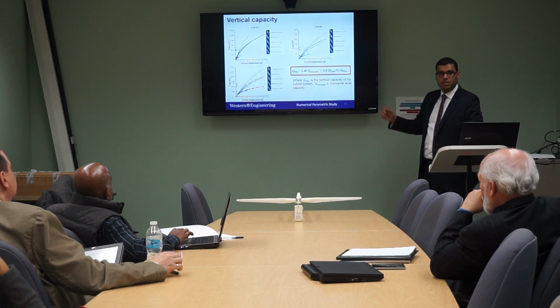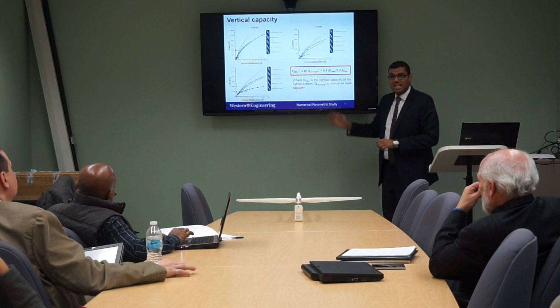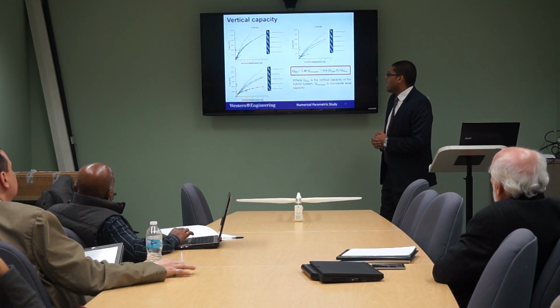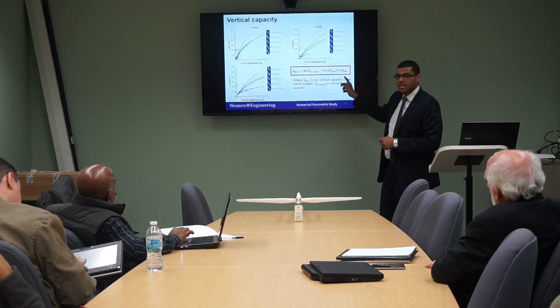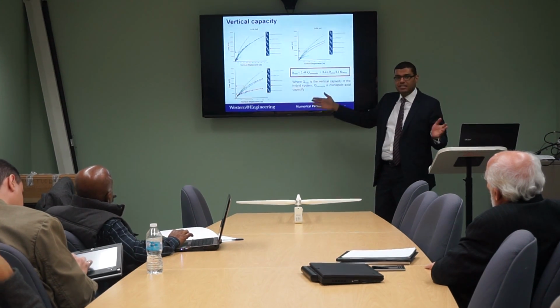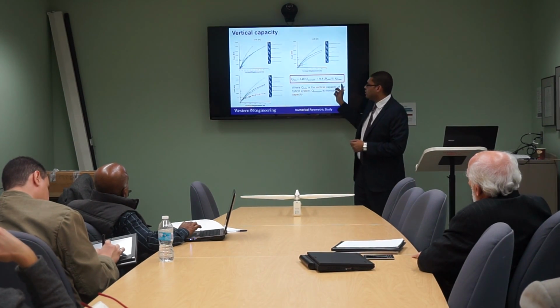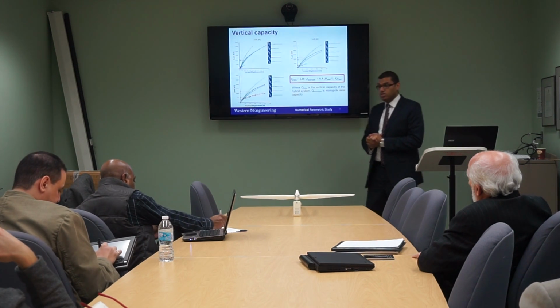After these several cases analyzed by the Abaqus model, we were able to present this equation as an empirical estimation for the vertical capacity of the hybrid foundation system. We can see here this relation between capacity of monopile and capacity of plate depending on the relation between plate diameter and pile length. So at the beginning, any designer will be able to use this equation to know the vertical capacity of this hybrid foundation system.